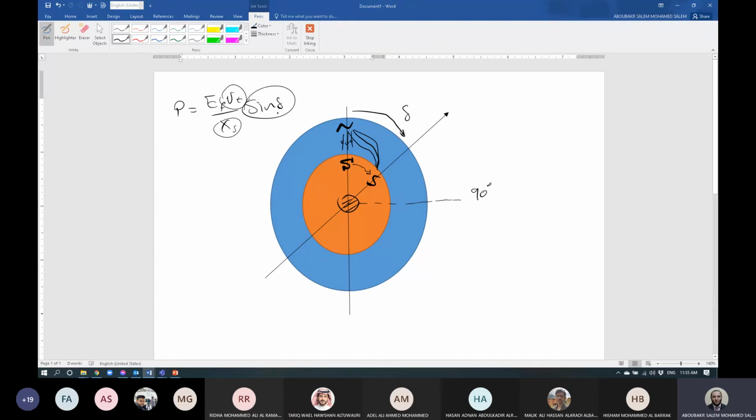In order to achieve a certain range for delta, what you can do is to control the excitation voltage. Is it right, شباب? Yes. Is there any other way, شباب, now? Only we can control X by decreasing X. However, decreasing X needs extra actions. We will see now how we can do that.